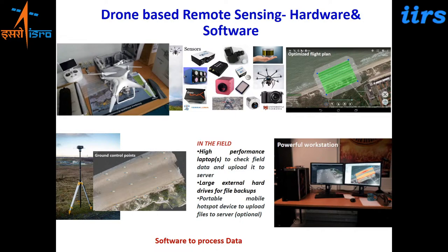So this mission planner allows you to plan the whole flight mission by selecting and defining the important parameters which are required to get successful results or data from the drone flights. So you need to understand these parameters, which will help you in getting good data sets from the drone platform.